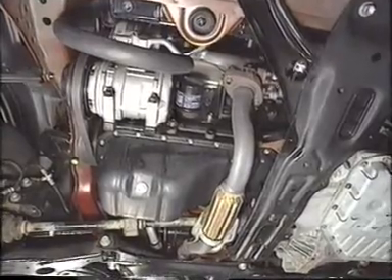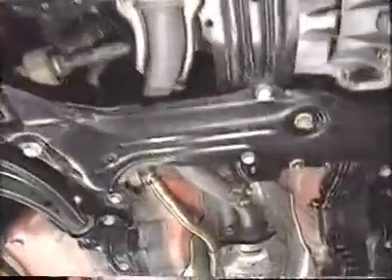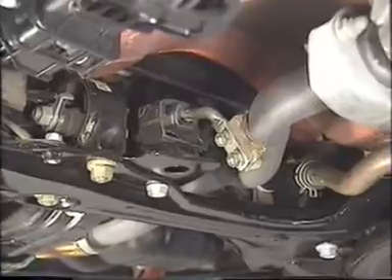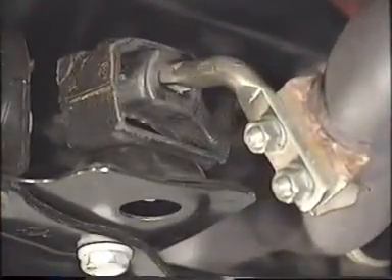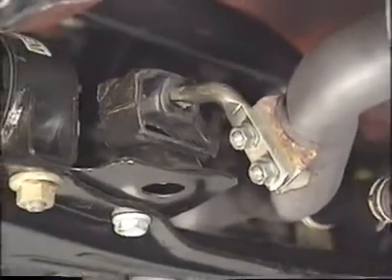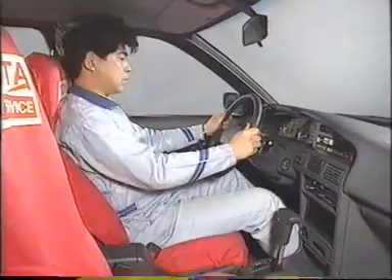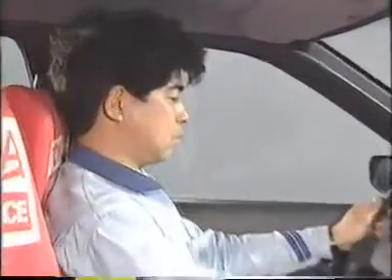The engine vibration causes the exhaust pipe to vibrate. The vibration of the exhaust pipe is transmitted to the body if the exhaust pipe support is not fitted correctly. The body begins to vibrate, causing the air to vibrate also. This vibration is heard in the form of sound or booming by the driver.